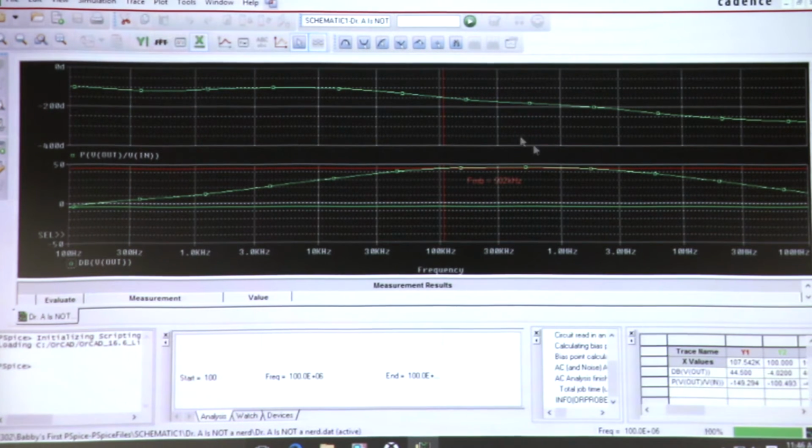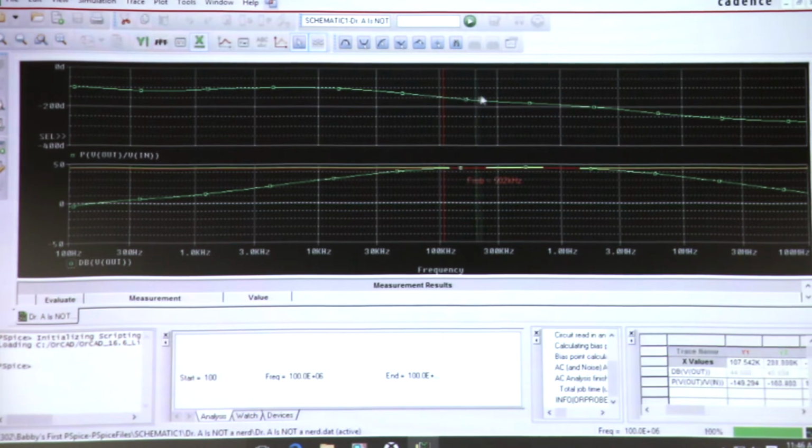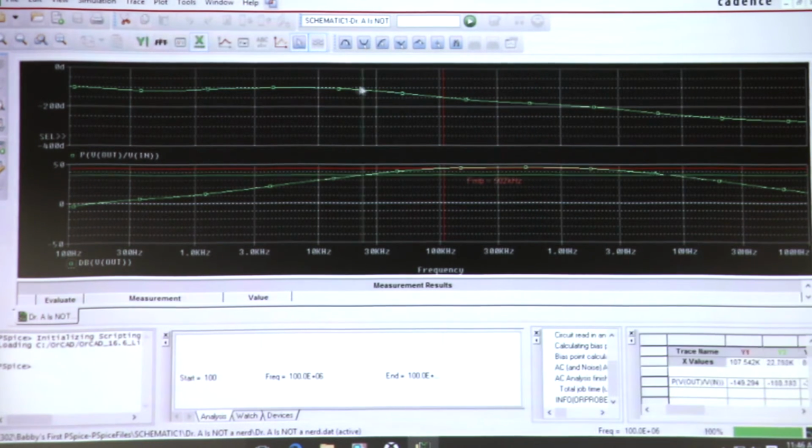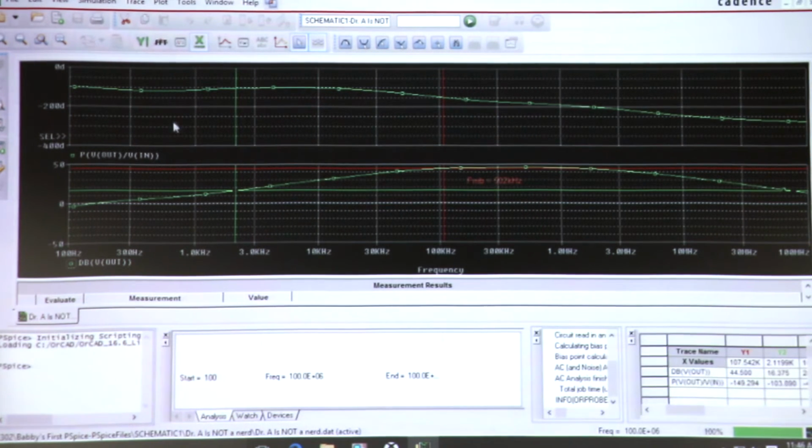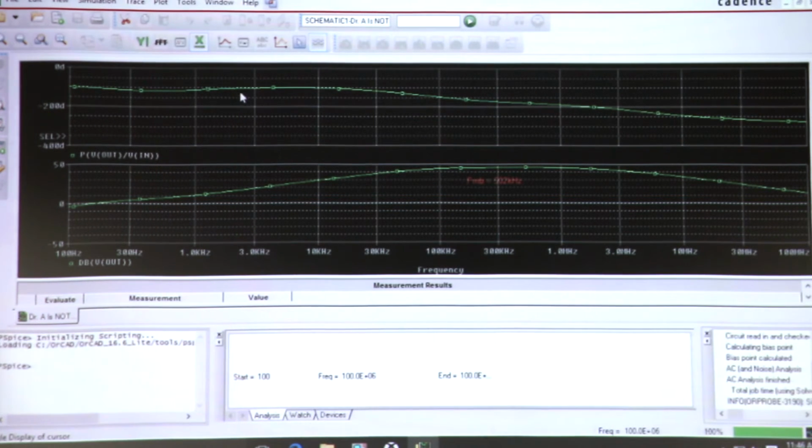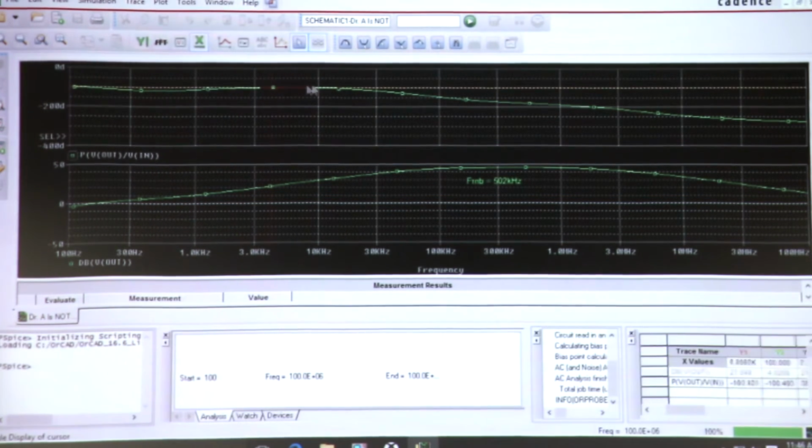So this is good for finding the phase margin, right? Because we can navigate to where we have the zero crossing and then evaluate exactly what the phase shift is at that point. Yeah, turn off these cursors. And you can add arbitrary lines and stuff like that, but you don't have to worry about it. These cursors are pretty handy. Okay, so that's the AC sweep.